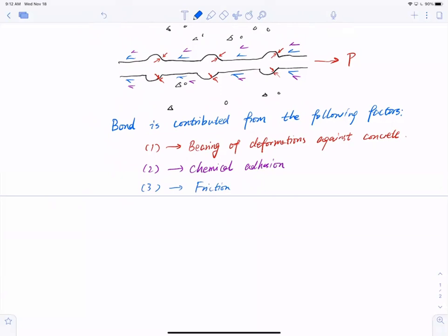Very important assumption here though. In RC design, well, in research it is a different story, but in RC design, we assume no slip. What does this mean, no slip? No slip means there's no relative deformation between the bar and concrete. They're together, okay? This is very important, meaning that the resistance paths between the bars and concrete are fully transferred. There are no stresses lost. Hence, no slip.